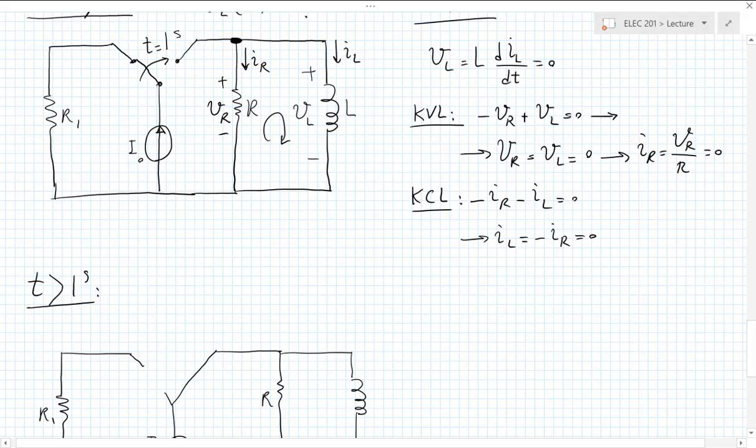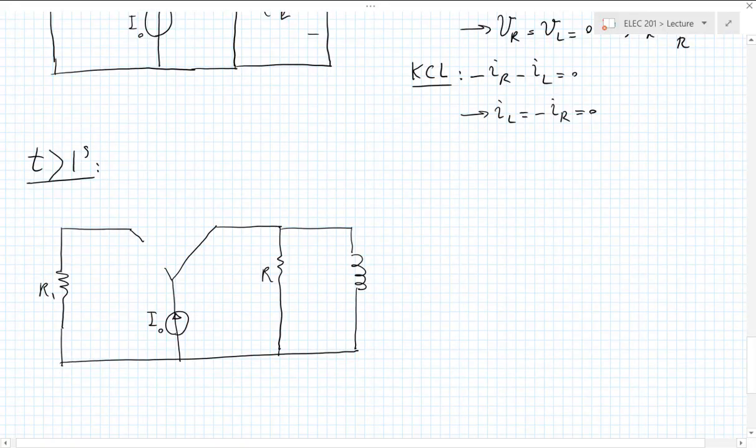that I'm pointing at, going from no current in that branch to all of a sudden I naught. So you might say this is a step change in that branch, right? So again, I'm looking at a step response in this circuit. So all of a sudden, the current here is all I naught, because this is now open, and this is the closed switch here. So I have I naught going like this.